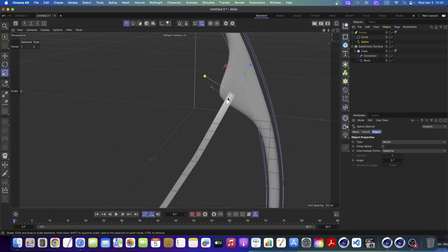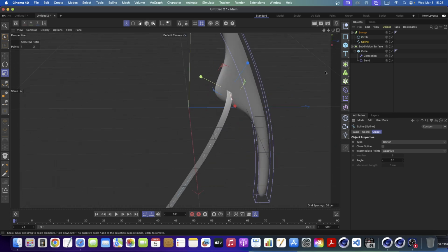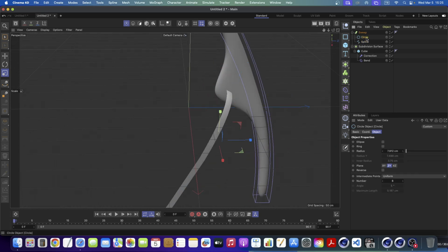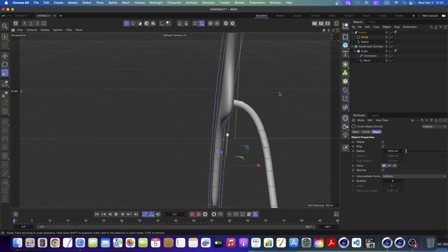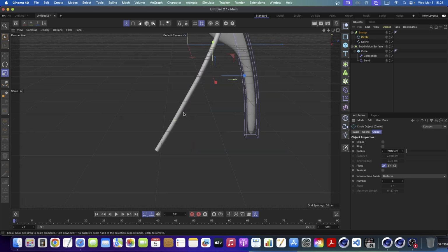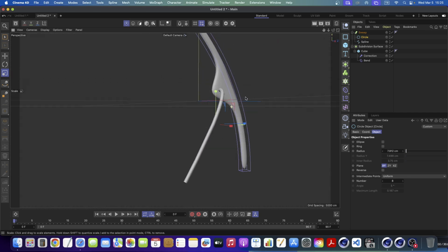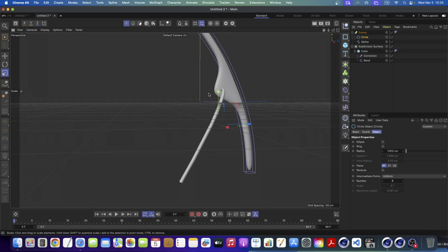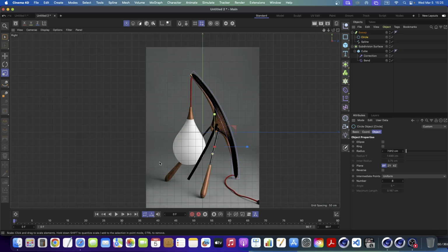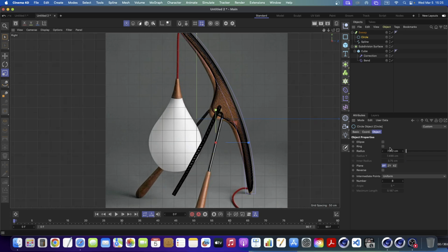And then we can see that okay, something is not right. So it's probably the placement of the circle. So I go to the circle and go to the plane and change the direction to XY, or plane to XY, and it's done. Okay, so more or less this is, let's see how it views. Okay, this is too thick, maybe let's make it 6, much better.